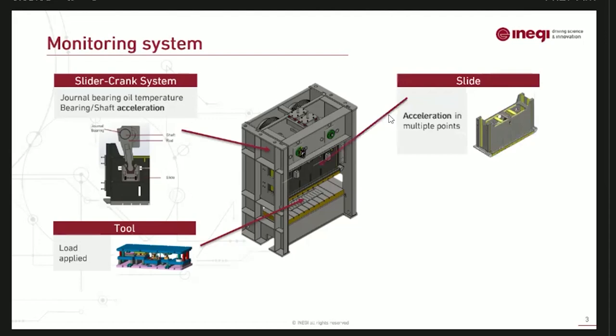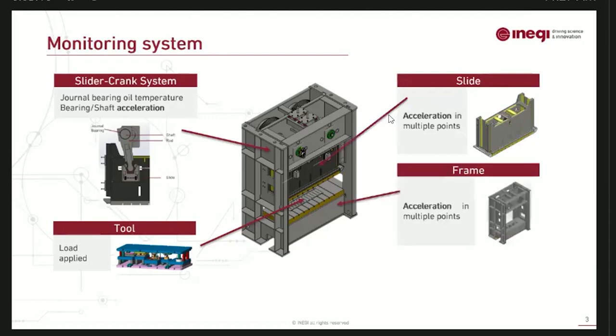Then the slide and the frame are structural components that are connecting all the other components. We thought of measuring acceleration there. And since this press is servo motorized and we have a servo driver, we can also use the motor data to monitor the condition of the other components.